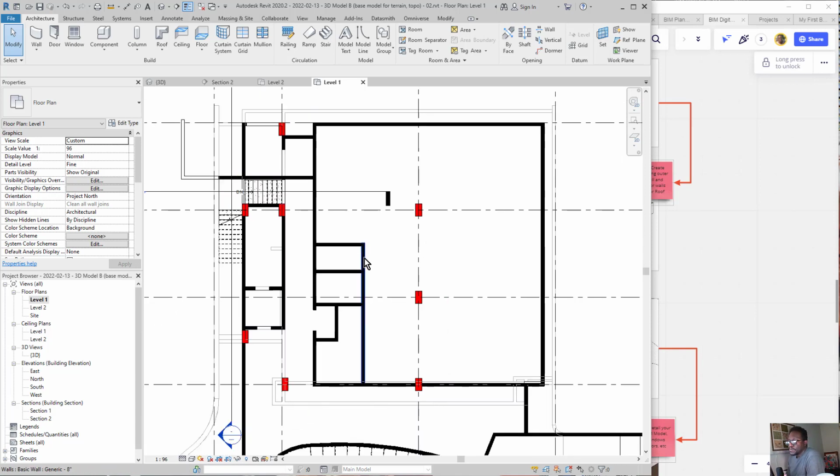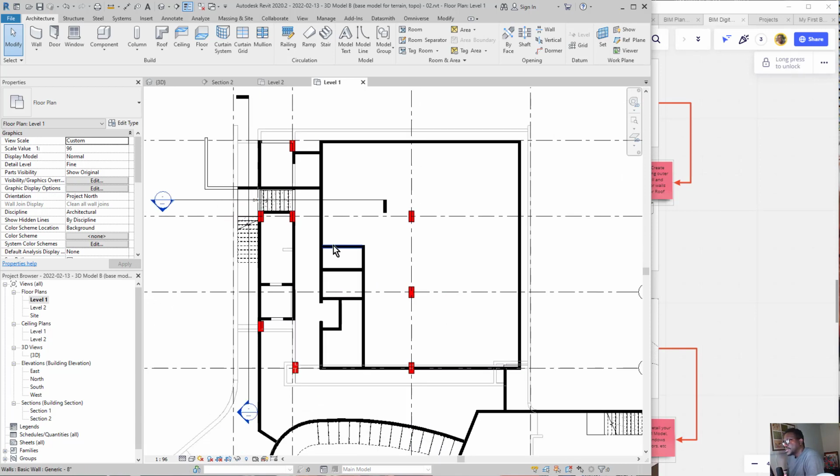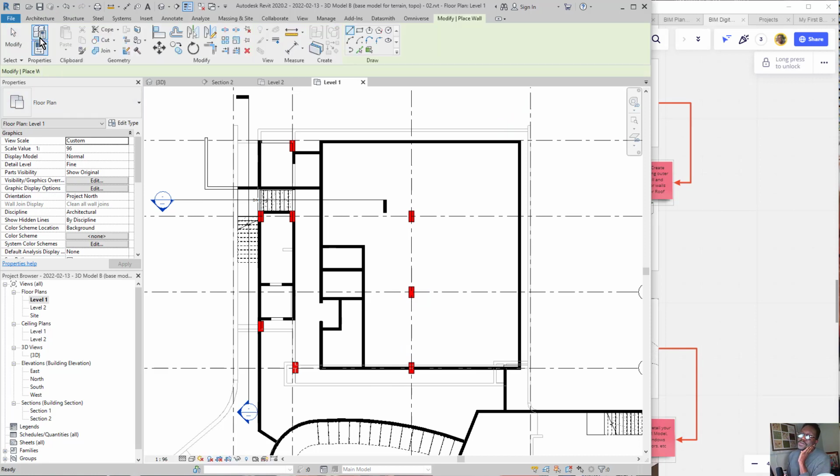As you perhaps would know, structurally not all walls would necessarily have foundations, but definitely the main structural walls, for example, the main outer walls, all our columns, they all will have structural footing, and we can actually find those options under our structural tab. But before we can add those structural footings, we need those walls to extend beyond the 0 level, right? And to do that, what we're going to do is choose our wall tool here, right?